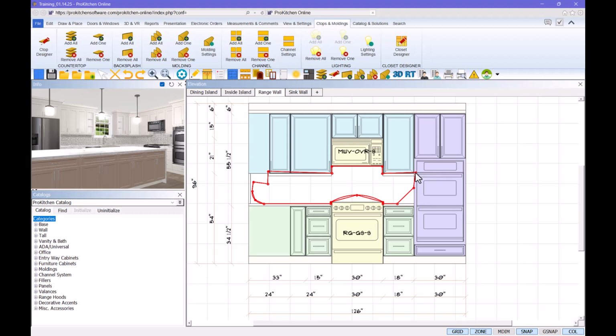The last option in this subset of edit tools is Delete Point. This tool will allow you to remove any accidentally created points or to smooth and straighten an edge of the previously created shape. When hovering over a point and activating the right-click subset of tools, then left-clicking the Delete Point option, the selected point will automatically be deleted, and you may continue making any additional edits.